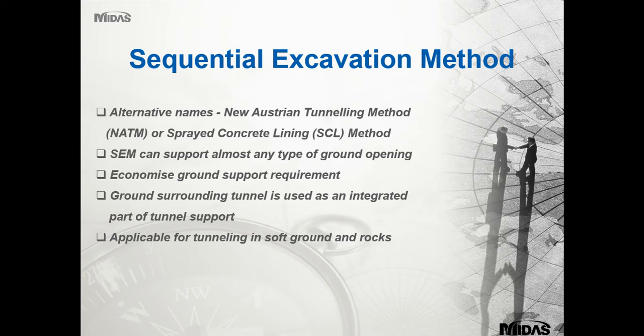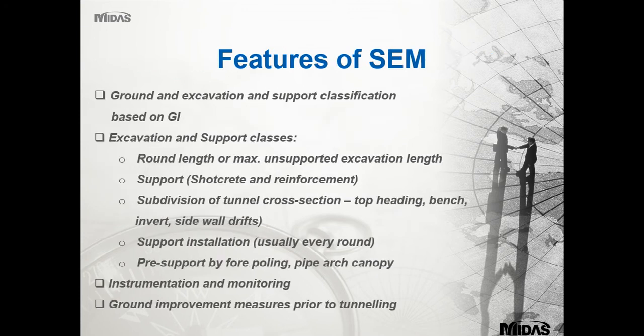You can economise ground support requirements with your sprayed concrete and also your rock bolts. The ground surrounding the tunnel is used as an integrated part of the tunnel supports as well, in the form of an arch, and the arch profile is self-supporting. It's applicable for tunnelling in soft ground and also in rocks as well. So those are just some of the features of SEM.